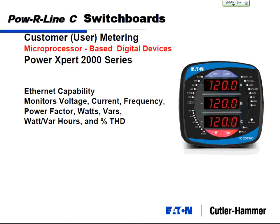We can take that same thing and make it Ethernet capable. And the trend of the industry is everything's going to Ethernet communication. So we can take this meter. We've got a communication card that slides in the back. You assign it an IP address, just like any other device on the network.